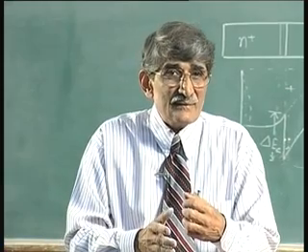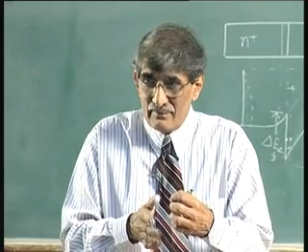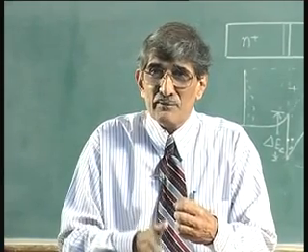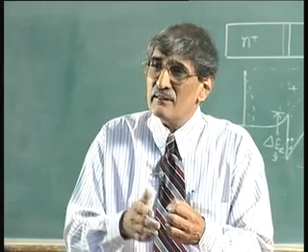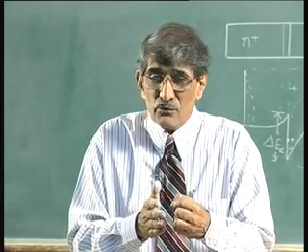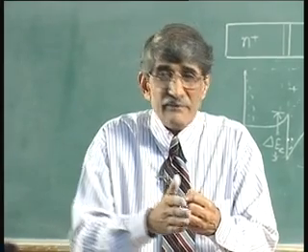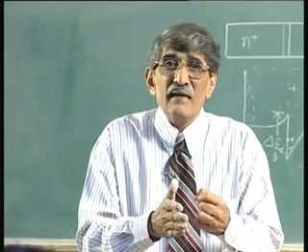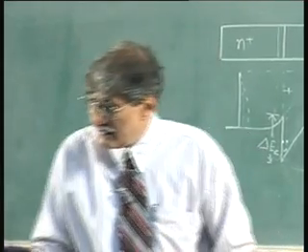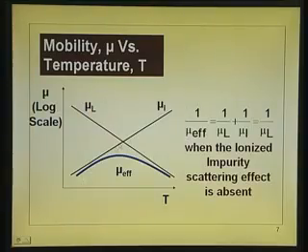At lower temperatures, this poor electron which is moving does not have that much energy, that much velocity. So, it actually gets scattered more, reflected more. The chance of scattering is more when you go to lower temperature. That is why at lower temperature the mobility decided by the impurity scattering is lower. Okay. And this is the other one.